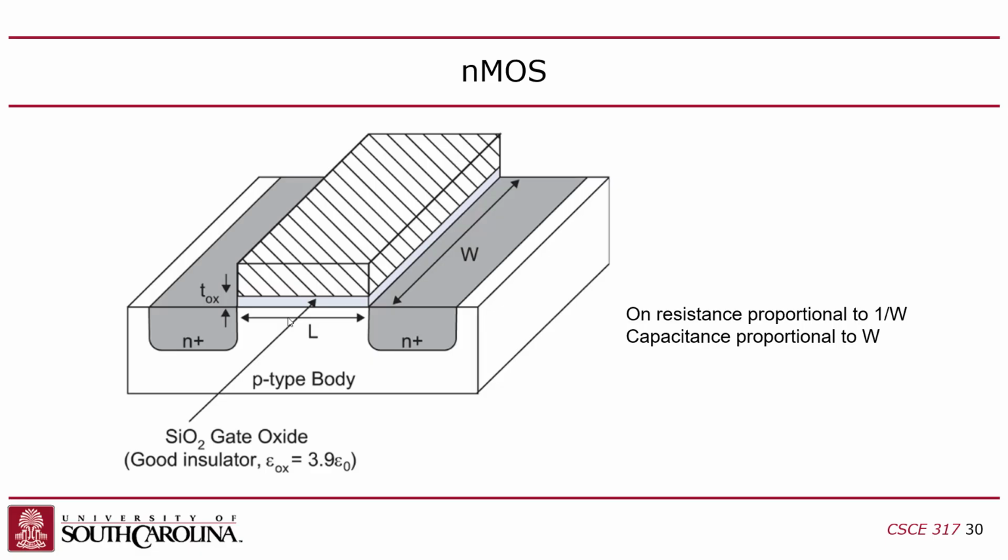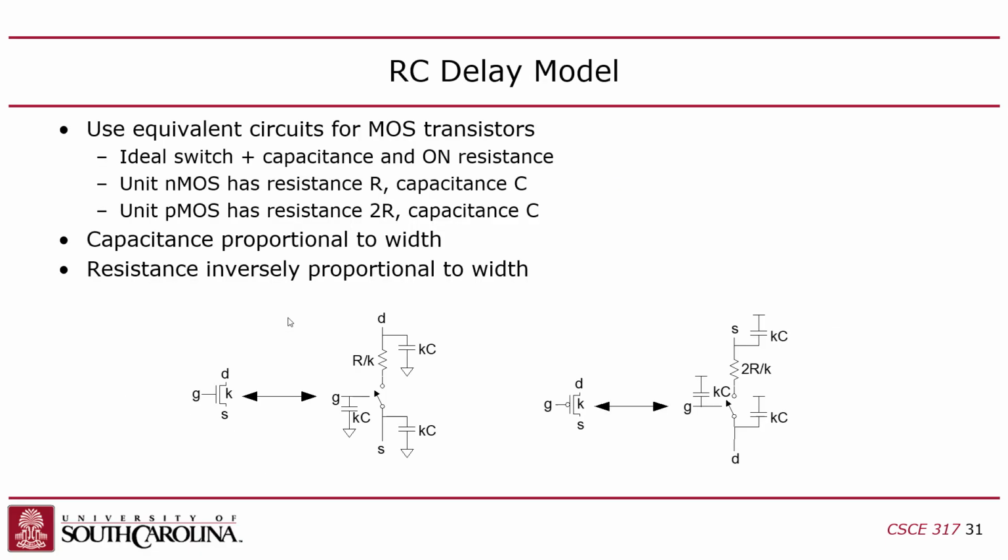And typically, in a standard cell library, like you'll go to TSMC and they'll give you the technology, you have to sign the NDA, they give you the technology library, you fire up Cadence, and when you put your transistors down or even your gates down, you can choose size. You can say, oh, I want a double size inverter, please. Boom, put down a double size inverter. It has double size transistors, and by size, I mean width, not length. The length is always minimum, width can be bigger, okay?